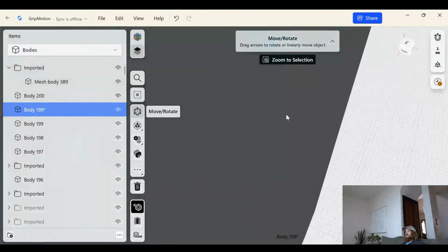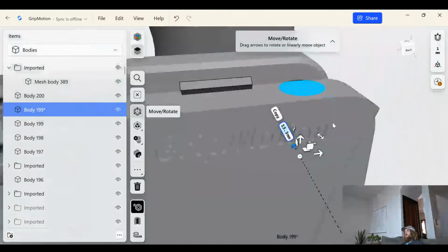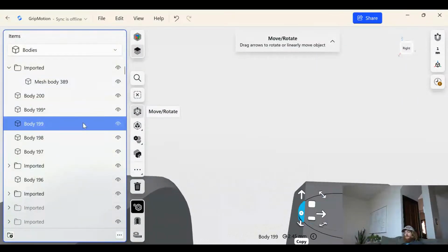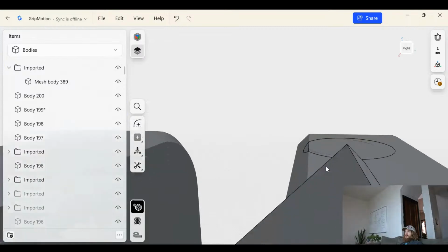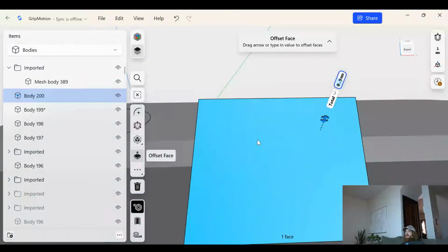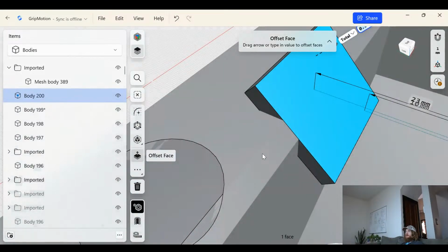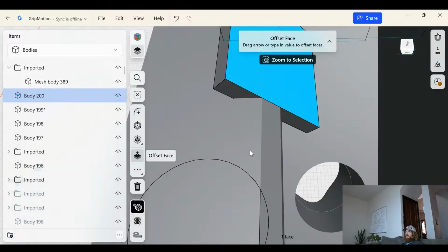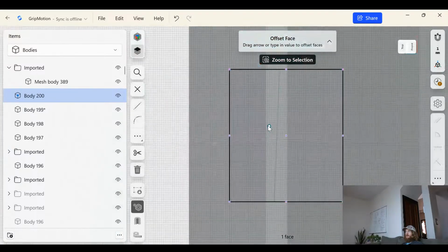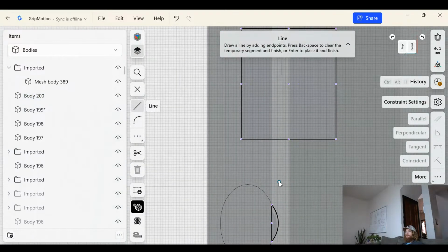First thing I did was I just filled the void. Okay. Then I built a secondary face over here by hitting spacebar. You bring your mouse over the face that you want to build off from. So if I want to build up here, I'll hold my mouse here. If I want to build on this angle, square to this face, I'll put my mouse here and click space. Okay, you'll see that on the right hand side of my screen.